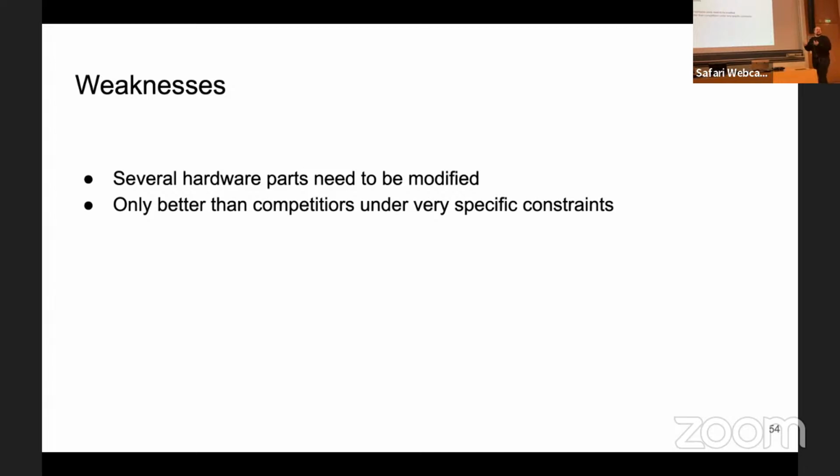All of the data is stored in row 100, and there are several cache blocks in that row, and we care about several of them. One time we look at data that's in one cache block and it's stored in sectors 1 and 2, and then we look at a different cache block in the same row and it's stored in sectors 3 and 4. Then in that case, before we activate that row, we have to activate sectors 1, 2, 3, and 4, because that's the way we would do it.